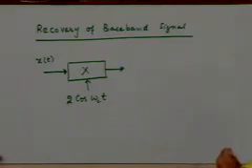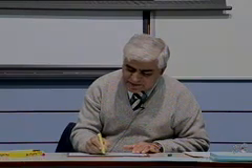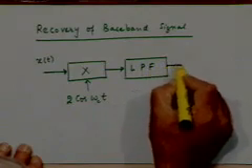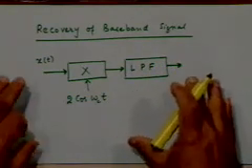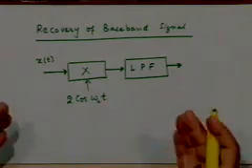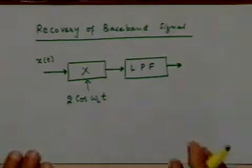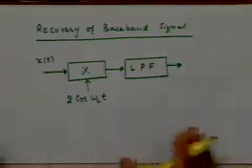So what you need to do is retain the component which is centered around 0 and remove the component somehow which is centered around 2 omega c, which is very easy. So the second thing that we must have in the demodulator is a low pass filter to remove the double frequency component, right. So we will look at this operation mathematically next time, which is more or less obvious, and then discuss further about the pros and cons of DSBSC modulation and demodulation. Thank you very much.